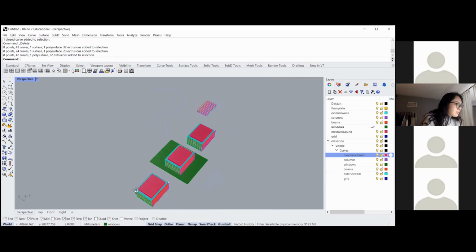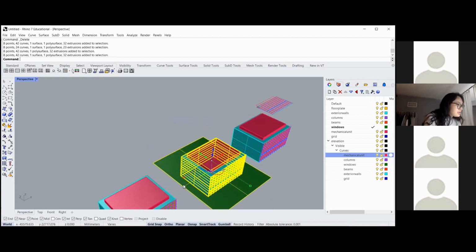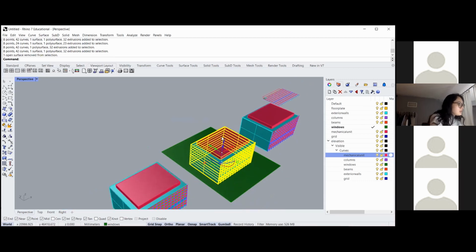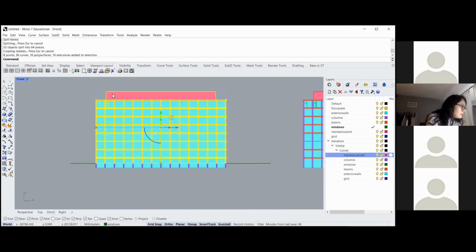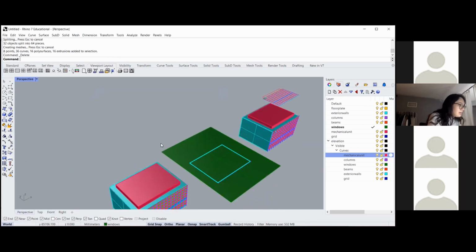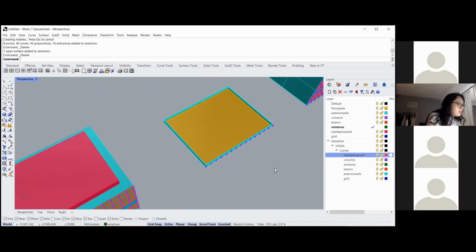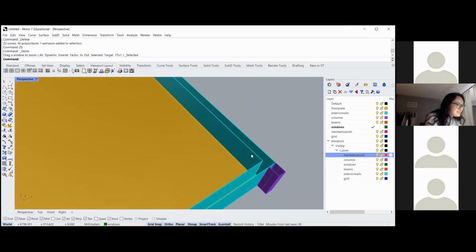Yeah. So I'm going to select the object like this, and then I'm going to deselect the plane by holding down Control and clicking the plane. And then I'm going to go split. I'm going to use my plane as a cutting object. Then from the front view, I'm going to select everything above that plane and delete it. And then I'm going to delete the plane as well. And this will give me my floor plan. There's nothing really interesting about it because we didn't do the inside.